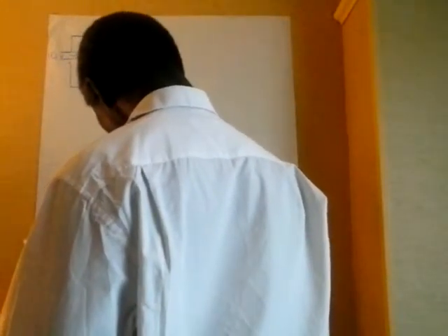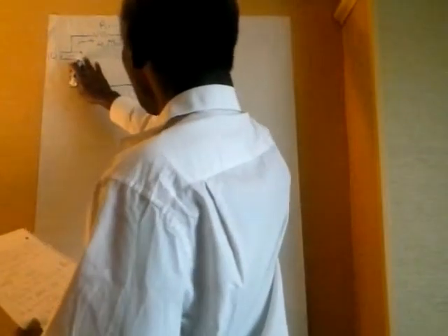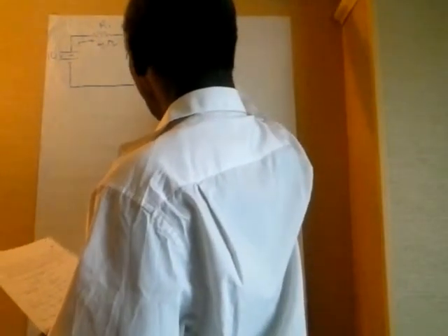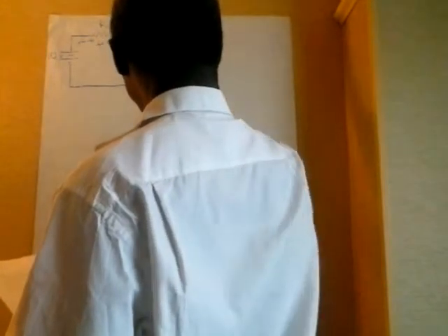So we find now the Thevenin voltage. Now the Thevenin voltage is the same as the voltage across this resistance here, R2. And you know that voltage across a parallel resistance is the same.